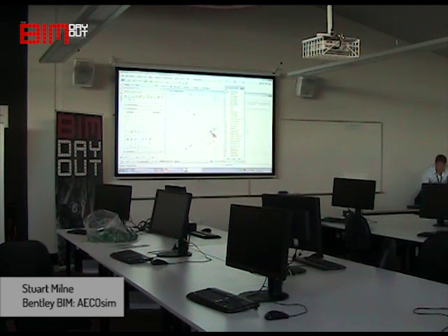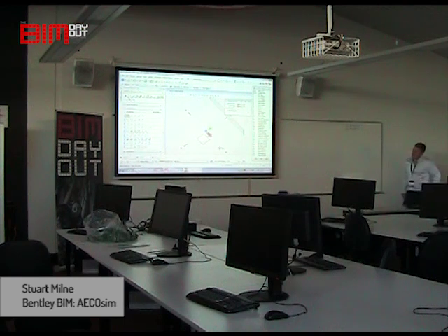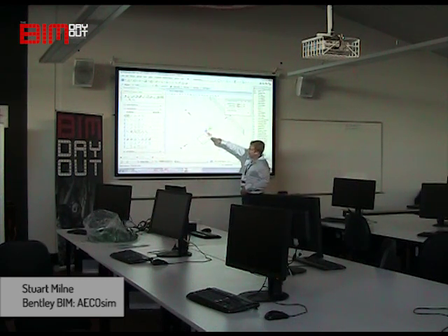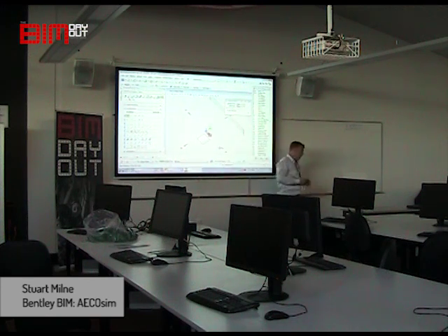Going back to our model here, which is over to the side. Okay, let's say, for example, we wanted to place a line that came directly up the z-axis. What we can do, go back to your face smart line tool and hover over the edges of the square. And what you'll see is when the snap point is found, we get that sort of yellow cross lighting up. When it lights up, click with the left.